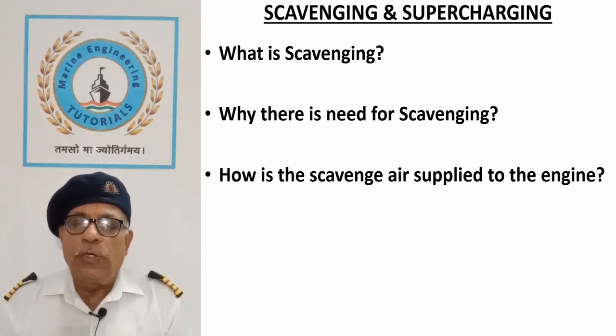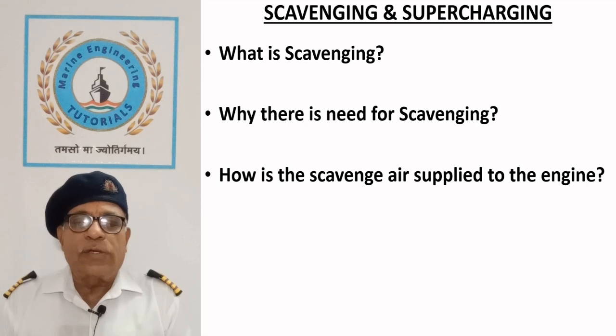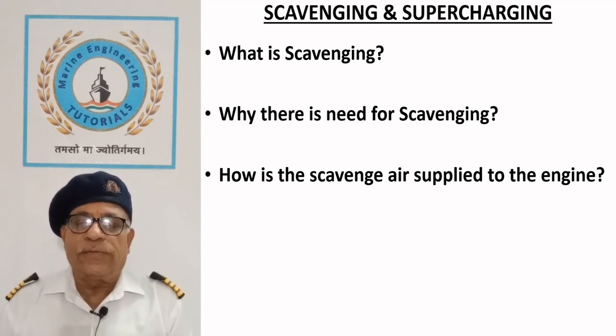A turbocharger is used for supplying scavenge air to the engine, which consists of a centrifugal compressor driven by a gas turbine using the engine exhaust gases.